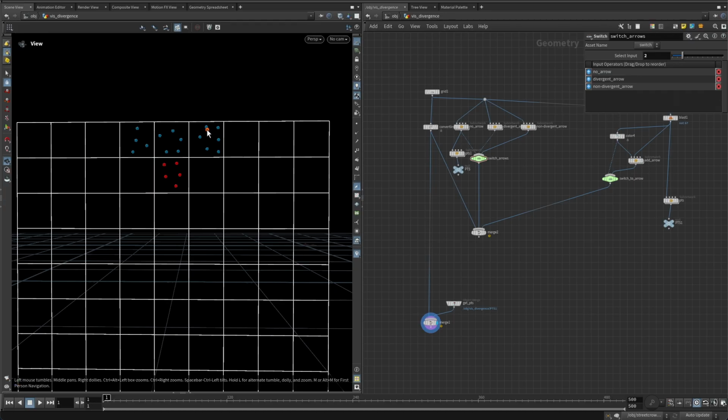The good thing about that is that you still keep some of that individual motion and you're getting that averaged motion added on top. So you're getting both of them basically. This is good to keep individual splashes or individual particles flowing in their own directions and so on. This method is called the FLIP method.